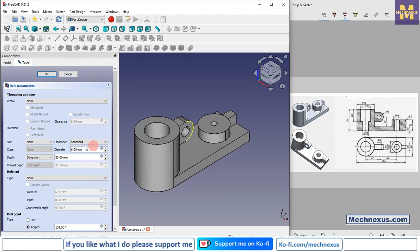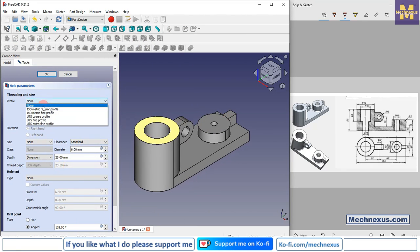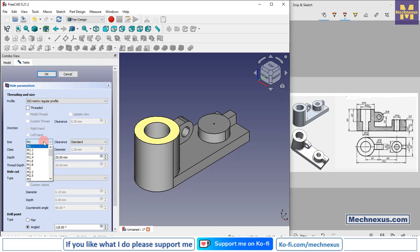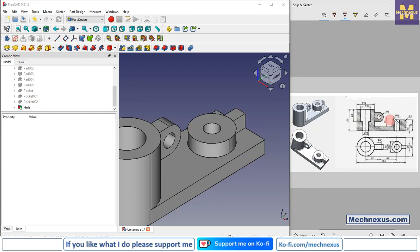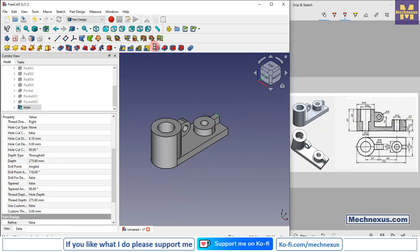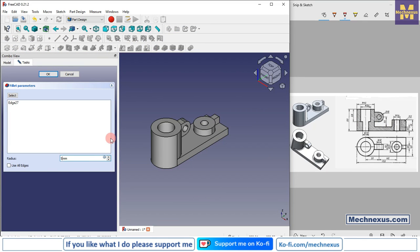because this is the tapped hole. So here we will select ISO metric regular profile, and from here I will select my tap size M10, and it will be through all, say OK. Now we will provide a fillet of 5 mm to this edge. So select the edge, click on the fillet, and provide the value of 5 mm, say OK.